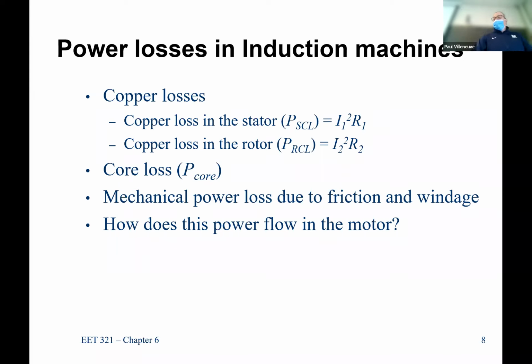I worked, this is a long time ago, in the nuclear Navy, where they have submarines. One of the key things about a submarine is being quiet, right? You don't want to be tracked. The biggest noise signature on a submarine is the propulsion system moving through the water. What sound you get is not the impeller, as long as you're not going too fast, moving across the water. It's actually the vibrations given off because the shaft is sitting around some bearings. That noise signature is what can give off the location of a submarine.